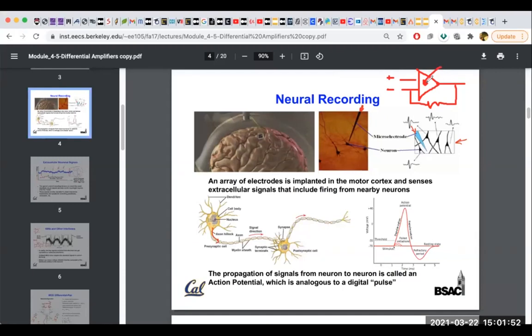And what was the purpose of operational amplifiers? Why do we use this differential signal structure? We want to amplify the differential signals. So if I make this VID over 2, differential signal divided by 2, and if I make this minus differential signal over 2, the input will be plus minus minus, so VID. So we amplify the VID, right? This will be a function of VID. So A1 VID will be the output.